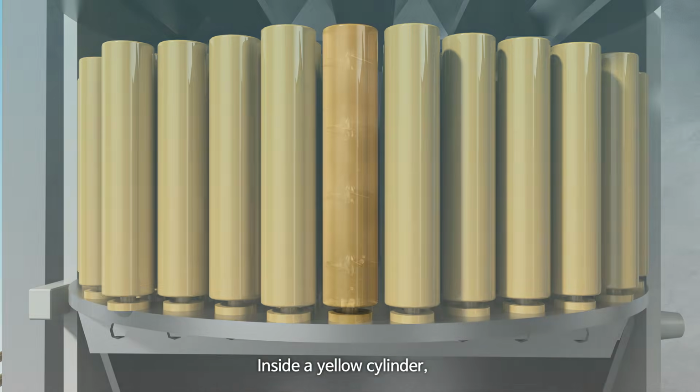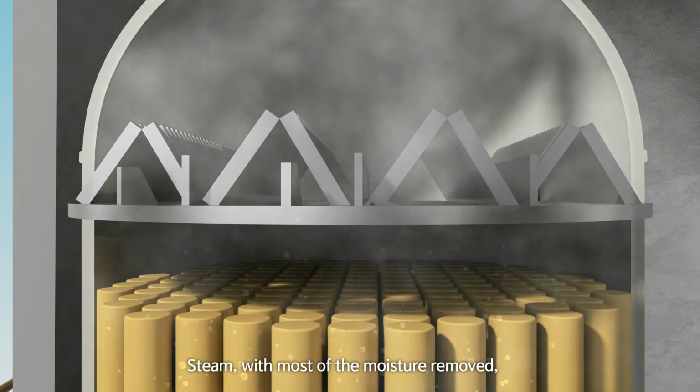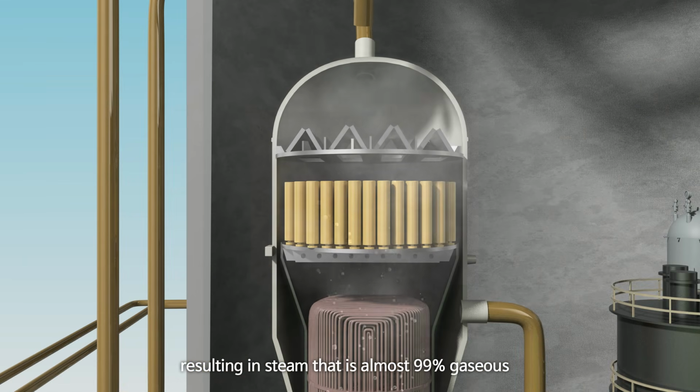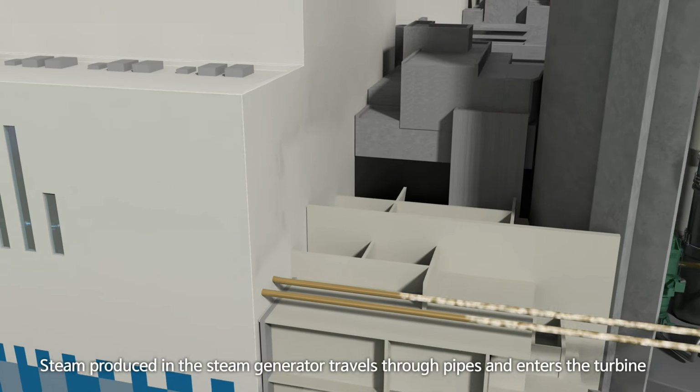Inside a yellow cylinder, there is a device shaped like a windmill that causes the moisture to condense back into water. Steam, with most of the moisture removed, then goes through another separation process in the grid-type separator, resulting in steam that is almost 99% gaseous. Steam produced in the steam generator travels through pipes and enters the turbine.